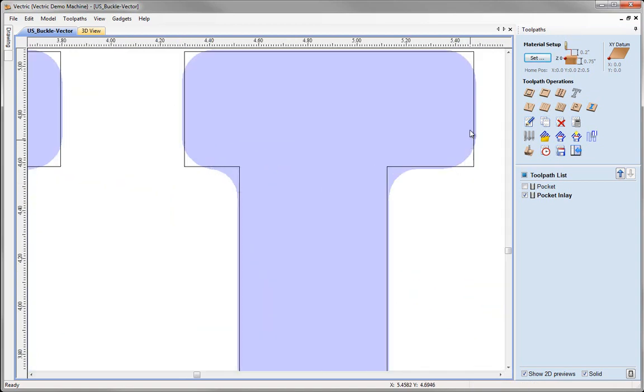So this roundness is to do with the shape of the tool itself. That's just the radius of the tool. But here you can see that it's cutting past this corner, and that's to allow for the fact when we cut this out that there'll be a radius on that internal edge. You can also see that this is coming a little bit past the edge of the part here, and that's that pocket allowance we set. That's why it's coming outside of the vector.